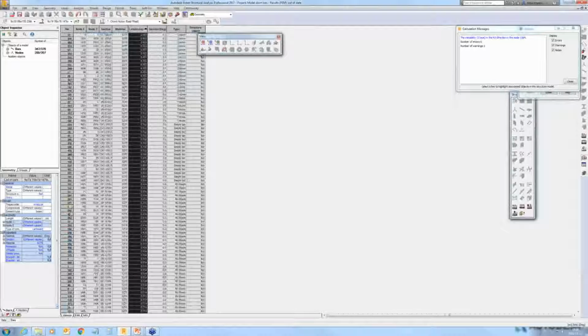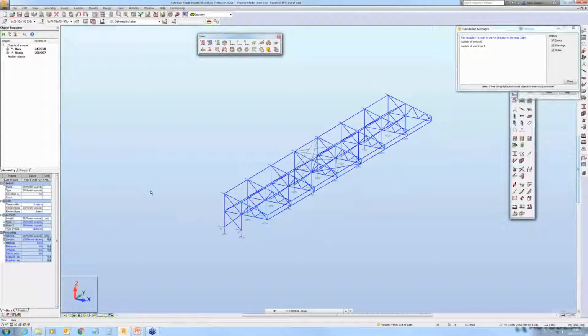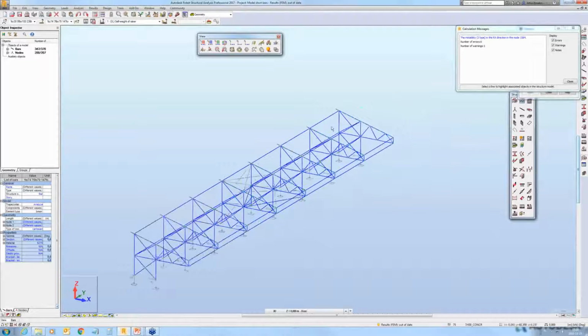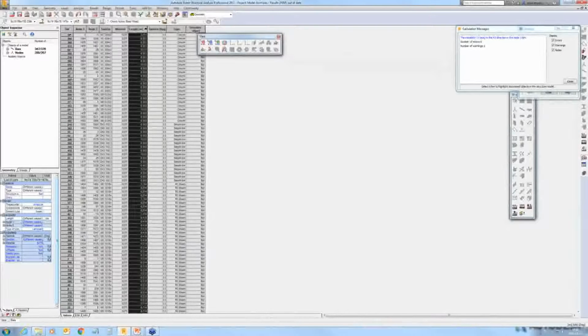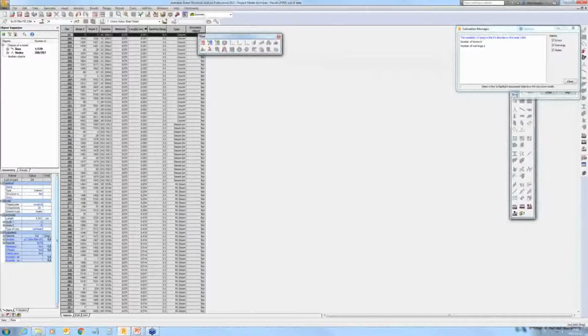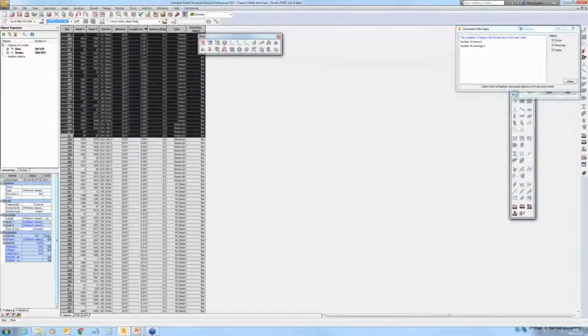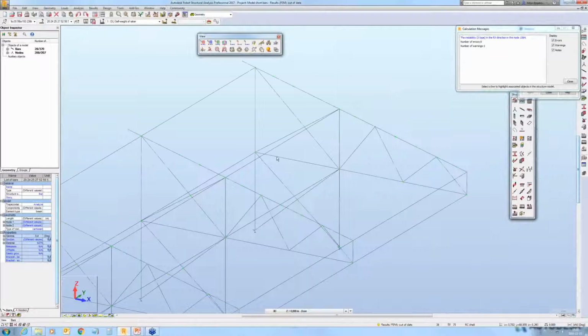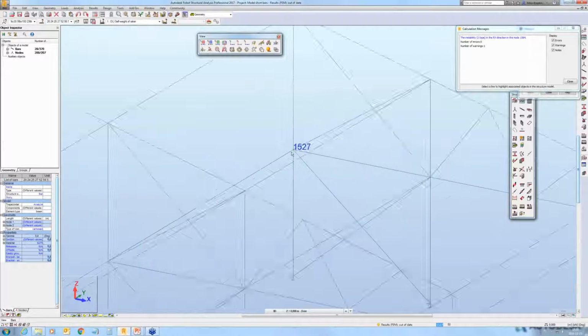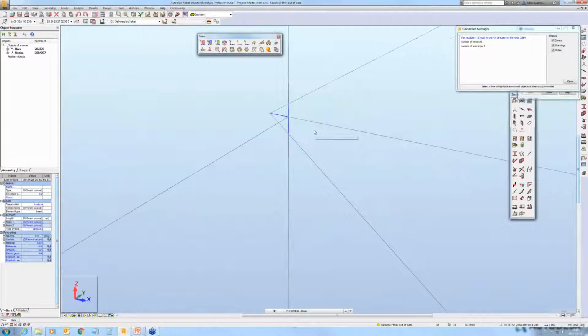And this, of course, is the issue for instability due to the very large difference of the stiffness of elements of the model. So if we go here, let's select those bars. We can transfer this selection, and if I have a look at the model, I can see where these elements are, and if we zoom, we can see what the problem is.